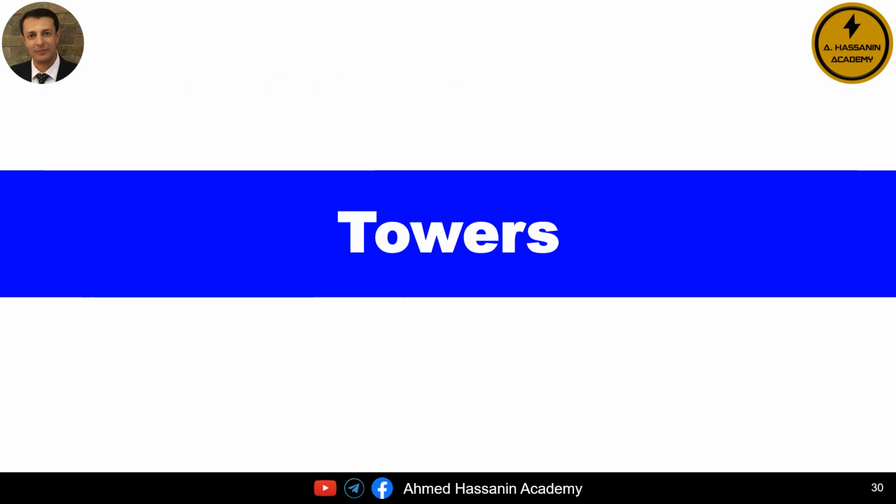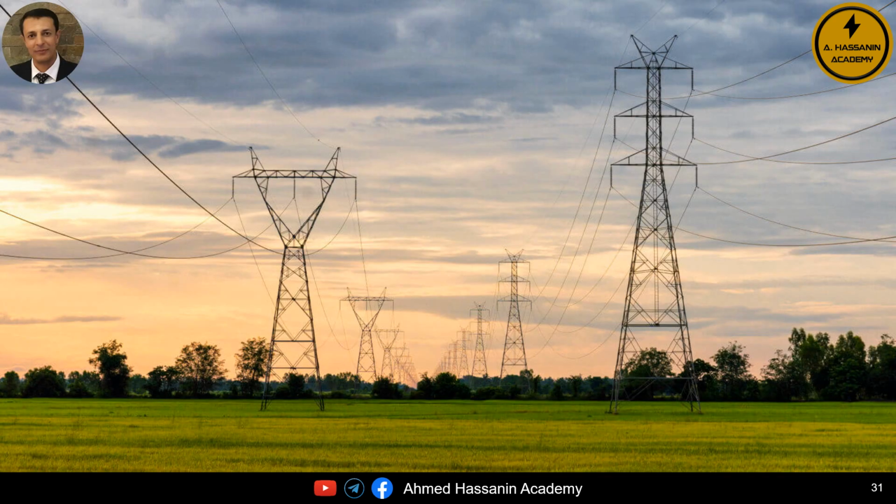Let us begin together and briefly with an explanation of the main components of the overhead transmission line system. The first component is the towers. The primary purpose of overhead transmission line towers is to carry and tension the conductors, wires, or phases in general. These towers must ensure that the conductors are maintained at a suitable and safe height above the ground. In addition, the towers must also ensure adequate safety clearances between the phases themselves.